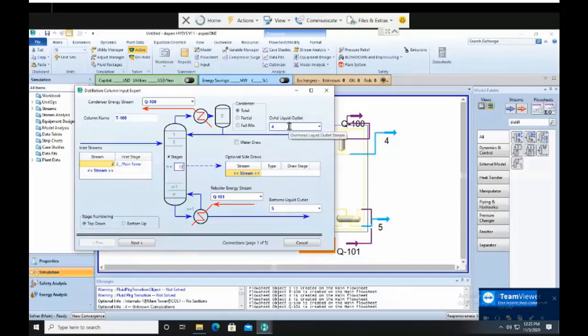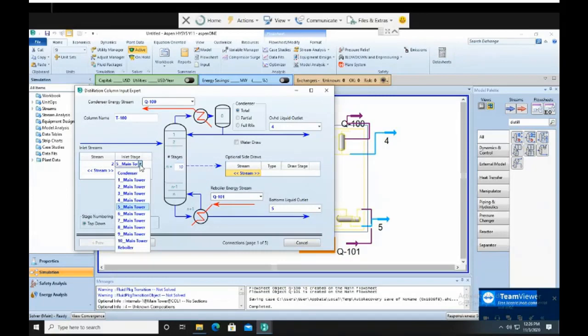So for example, methanol in this case, let's say we want it to be at 99%. So you cannot design your distillation column with the product purity at the top at 80%. Who would buy it? Because the customer wants it to be 99%, but you only managed to produce it at 80%. So that is not right. So how do you do this? You increase your number of stages. So we are going to see this later. Now, this one, the inlet stage also you can manipulate. So in this case, let's set it at stage number 6. The total number of stages is supposed to be 12.